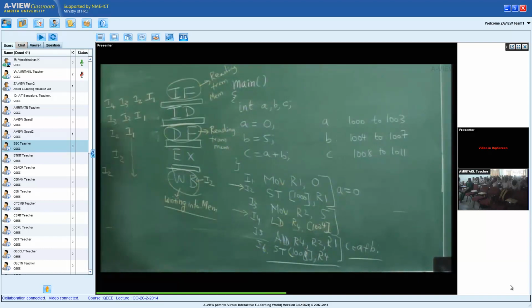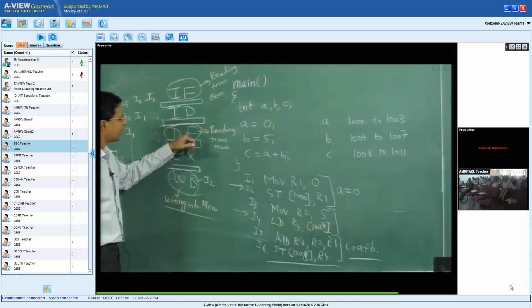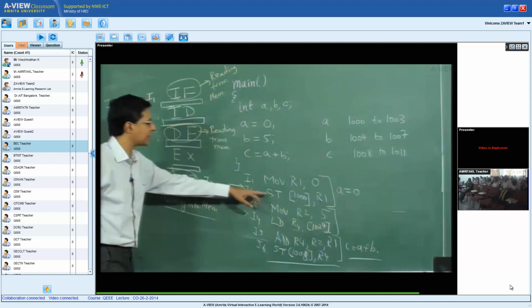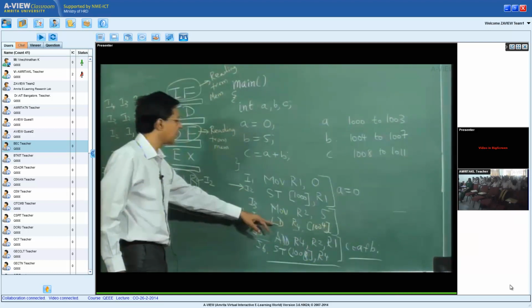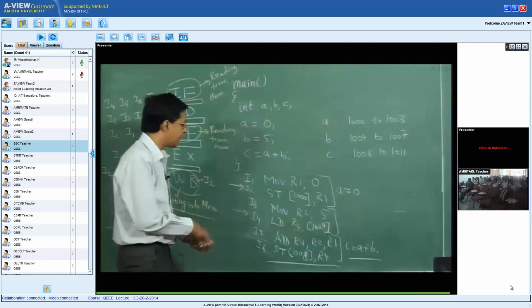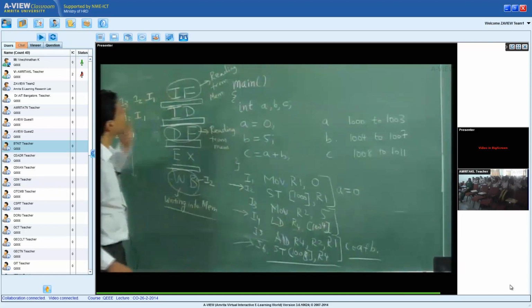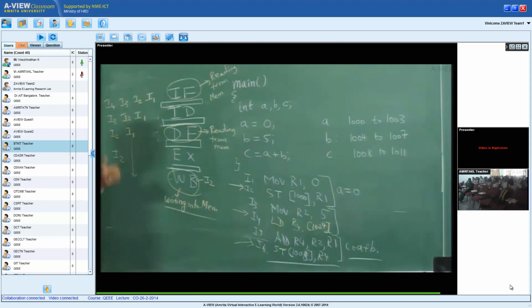So please look that there are three instructions. One instruction is writing into memory, one instruction is reading the data from memory. For example, I have a store here, I have a load here. The store is writing into memory while load is reading from memory, and this instruction is fetched from memory. I always read instructions from memory. So there are at least three instructions currently under execution in the pipeline that access the same memory.